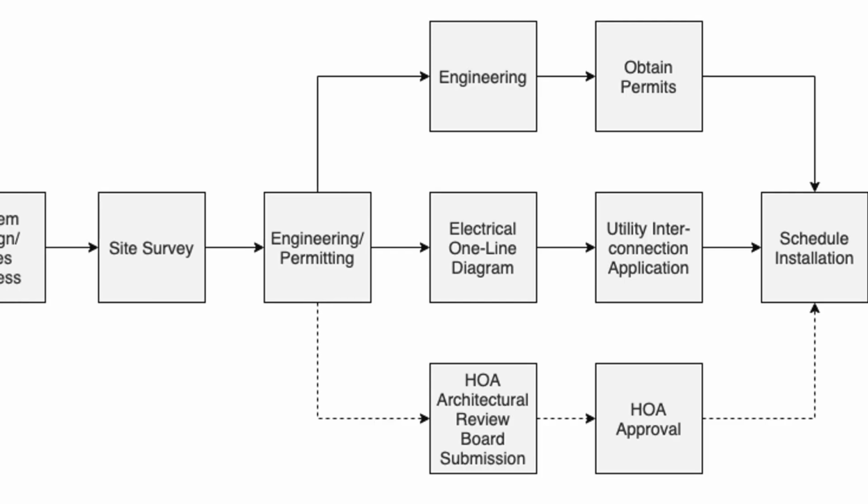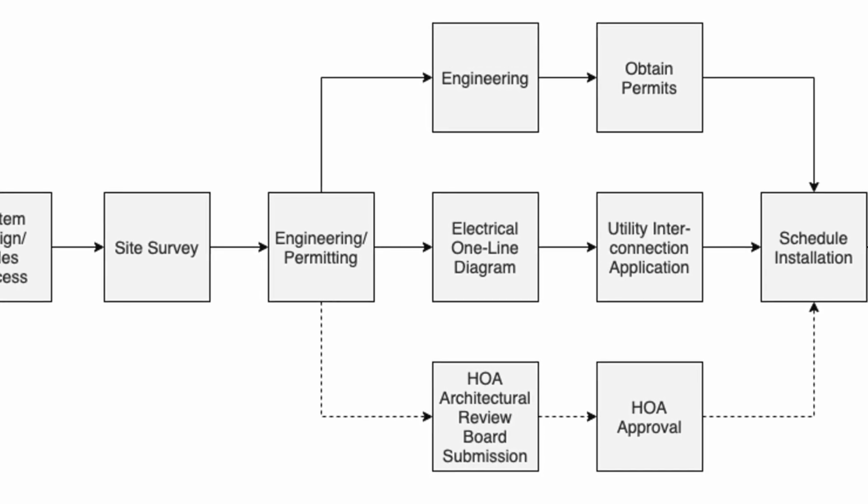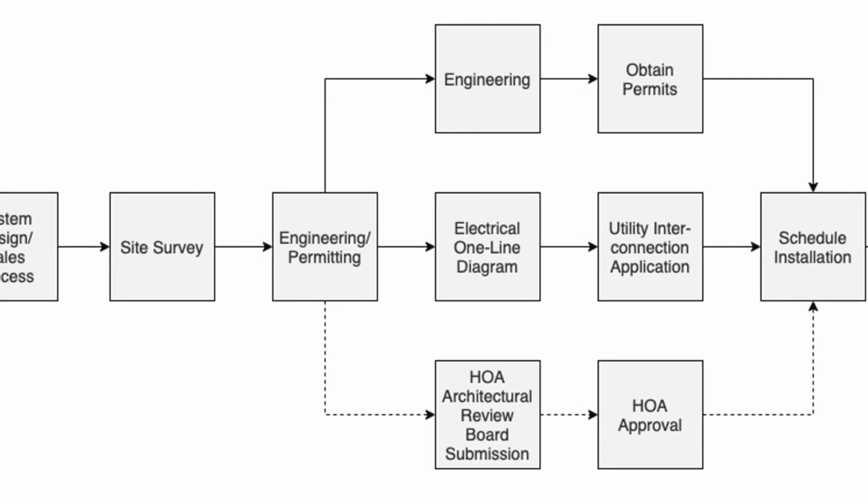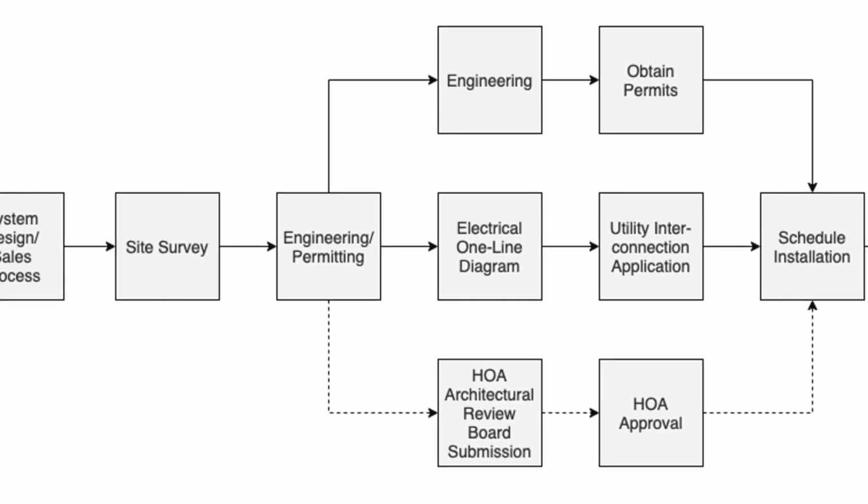After that information has been obtained on site during the site survey, things progress to the engineering phase, where our engineers will then go through a structural analysis, and they will also go through an electrical analysis. Now, during the structural phase, this is where things such as dead load capacity, in other words, what your roof can support from a weight perspective, as well as the wind capacity. So for high wind zones, hurricanes, storms, things of that nature, we're ensuring that the panels will not be removed from the roof in those types of circumstances.